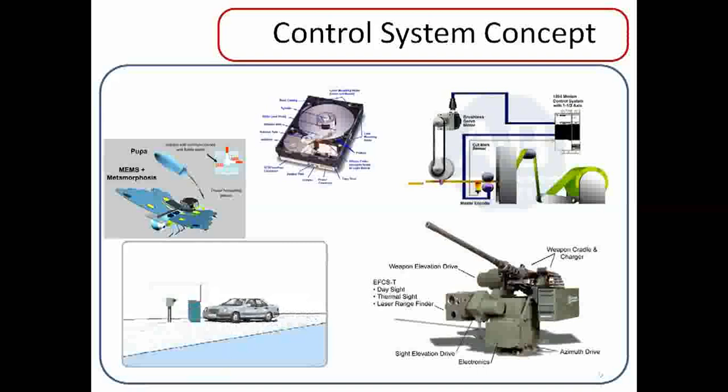Considering the same operation that you are visualizing on the screen as an open loop control system, when the sensor senses the car, it gives the signals to the gate that it has to be opened. But there will not be any feedback to the control system about whether the gate has been opened or not. It may get opened or may not, or it may be fully opened, or only semi or 50% of the gate lifted up. That doesn't matter in the case of an open loop control system.